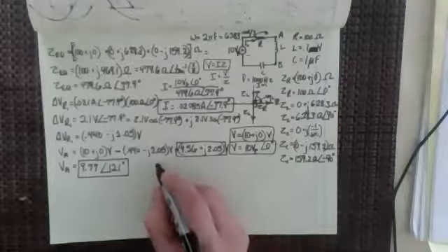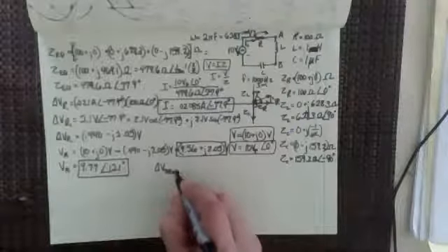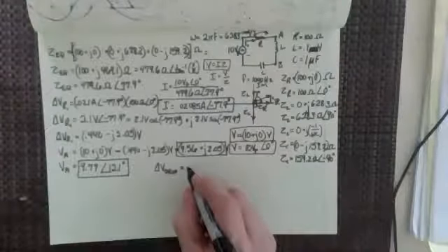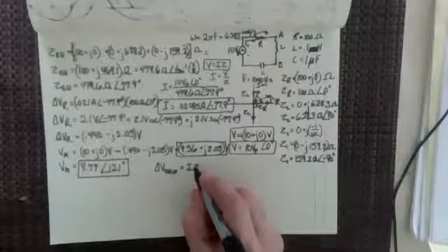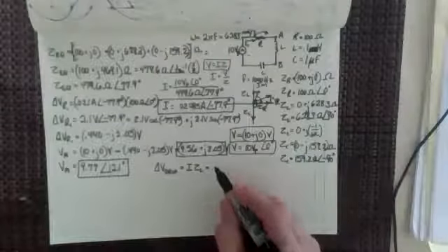And of course, to do that, the voltage drop, I'm actually going to write drop here across that inductor, is the current through the inductor times the impedance of the inductor, isn't it? That's going to be the voltage drop. Remember, we have to subtract that off the voltage that we got from A. So let's see how we've got this here.